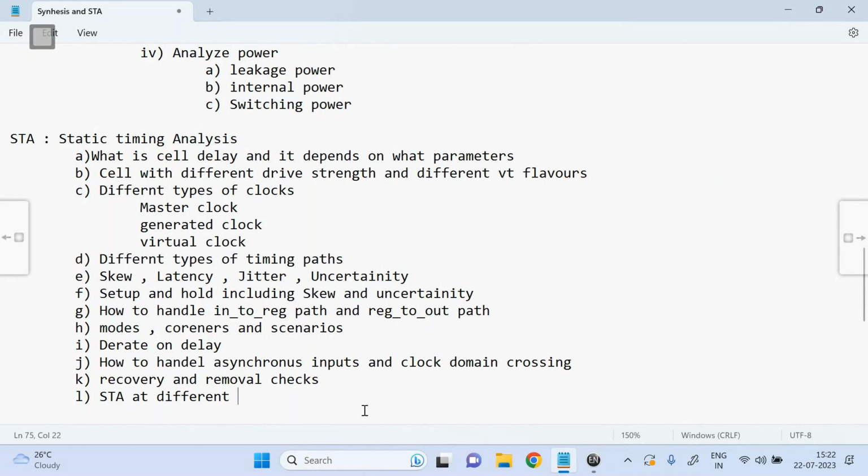During logical synthesis, we will get net delay from wire load model, and clock is ideal. After placement, we'll get wire load model from TLU plus file, but clock is ideal. After CTS stage, clock is propagated, but still we use a TLU plus file.